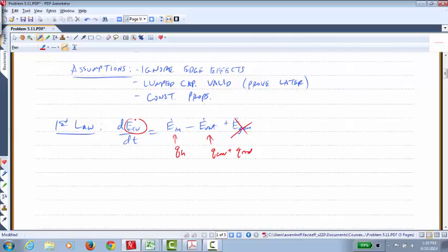The energy inside the control volume is going to be the mass times the heat capacity times temperature, since we're going to assume that all the energy within this control volume is thermal energy. And we know that q_h is going to be the heat flux applied over the entire surface area. Convection, we know, is h times A_s times T minus T infinity. What we're going to assume using lump capacitance is that the temperature at the surface is the same as the temperature everywhere else inside the base plate. And q radiation using Stefan-Boltzmann is A sub s epsilon sigma times T to the fourth minus T surroundings to the fourth.